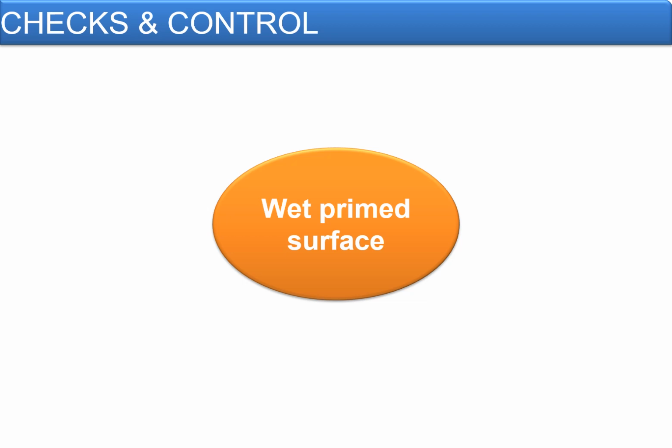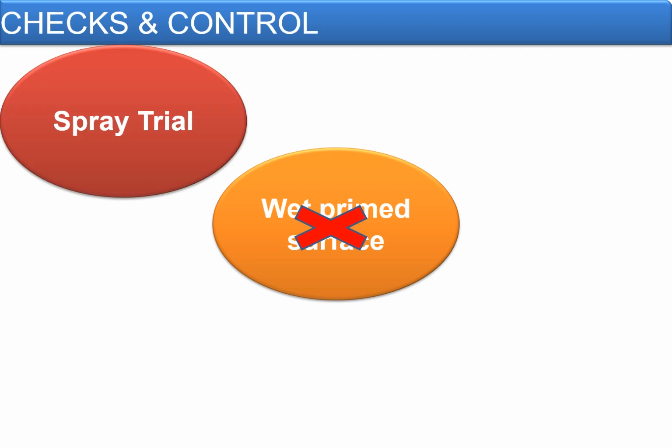Like any diesel or any oil leakage from any equipment on top of a prime coat or on top of the bituminous road, that is the DBM, maybe the DBM first layer, on which you want to have a DBM second layer. You have seen that after the completion of a DBM first layer and with the passage of traffic on that, you have patches of areas where some oil leakage has been observed. Then those need to be cleaned up properly before application of the tack coat.